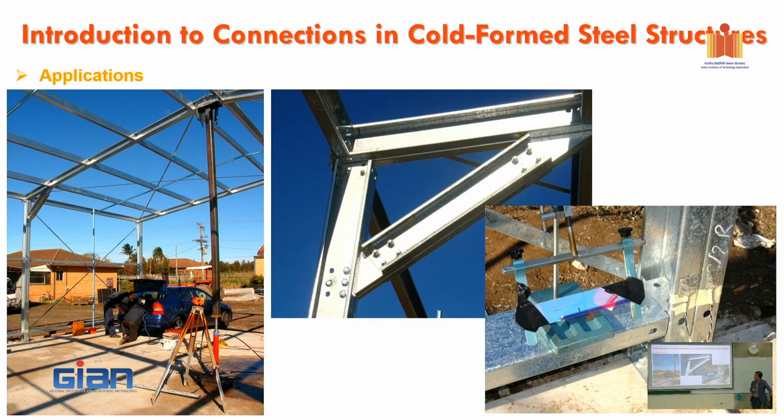Okay. Usually we recommend around 6 inches or 150 mm depth inside the concrete. There's some minimum requirement. I can't remember the number, but I'm sure. Most contractors just do not follow that. Okay. They only want 75 or less than that. And we find a hard time because the pouring of the concrete is also sometimes not right. The top 10, 20 mm is somewhat a lean concrete and it won't provide adequate bearing. So we insist on 150. But I am in a company in the US where they say that 150 is too much, they go for 100. Okay. But what is the practice in Australia?